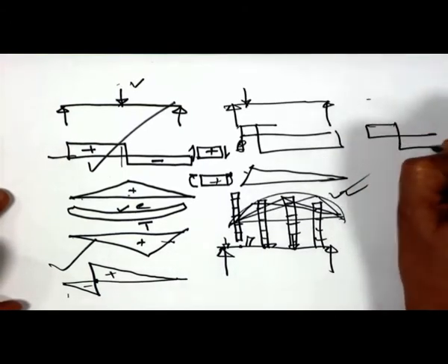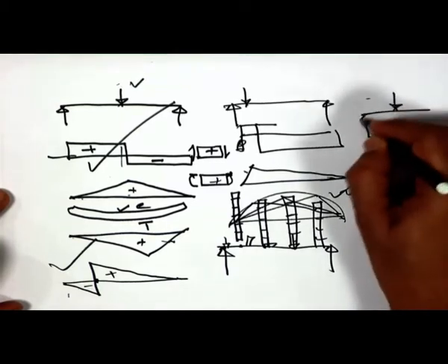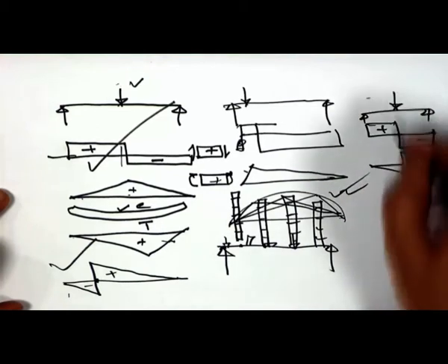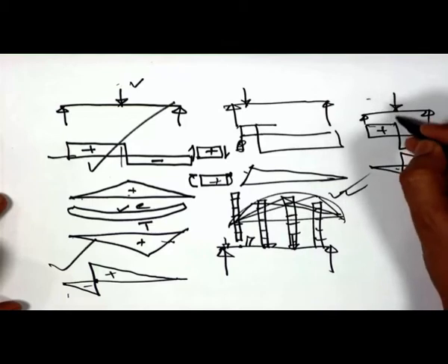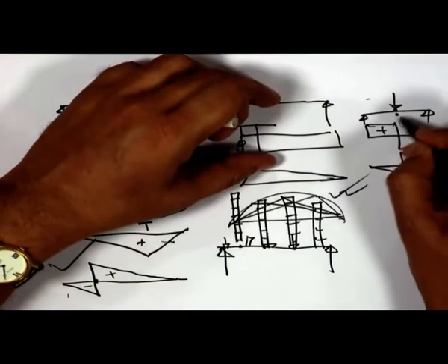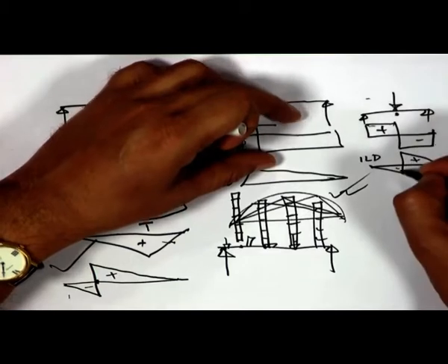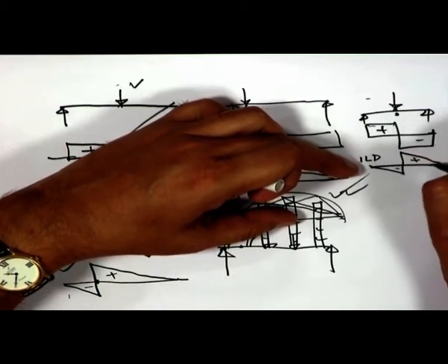For you this is a shear force diagram, with positive and negative shear for the beam which is loaded in the middle, and then you have, suppose, the influence line diagram for the shear force here, which is like this. Now it is very difficult to digest, because what I am doing actually is sitting here. This shear force diagram is completed. For the influence line diagram I am sitting here and observing how the shear force is changing there as the load moves in space.